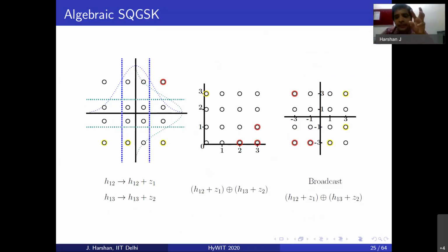That's easier said than done, but the implementation of this particular idea is fairly involved. The reason is, let's focus on the picture on the left here. We are at the phase of quantizing this channel H12 to the QAM point. Now, I would not like to quantize this to the QAM point. One of the main reasons is that the QAM point constellations are all uniformly spaced. And if these H12, H13 are all Gaussian distributed because of the Rayleigh fading characteristics, then the probability mass function induced on these discrete values is not going to be uniform.